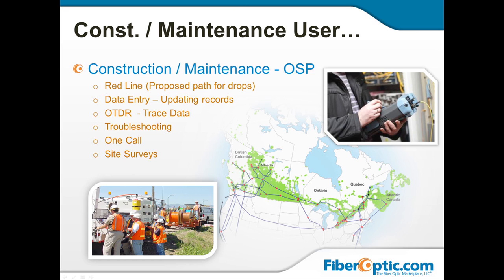I go to the head end, get to the patch panel, I shoot the fiber, and I know that I'm short. I go maybe 11 kilometers, and I'm supposed to go 20. And I pull out the trace, and I look, and I've got an idea of where I've got the break, and then I start pulling out the maps and trying to figure out how far 11 kilometers is on the maps from where I am, and all that time is spent and wasted.